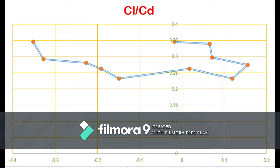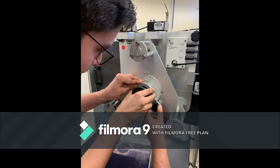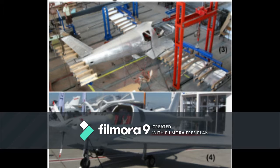The expression of aerodynamic forces and moments in the form of aerodynamic coefficients is very important in aerodynamic studies and calculation, simplifying them considerably. The aerodynamic force acting on an airplane can attain values in the hundreds and thousands of kilonewtons. The same force acting on the model of this plane which is being tested in a wind tunnel will be tens of newtons, but the aerodynamic coefficients for the airplane and the model will be equal.